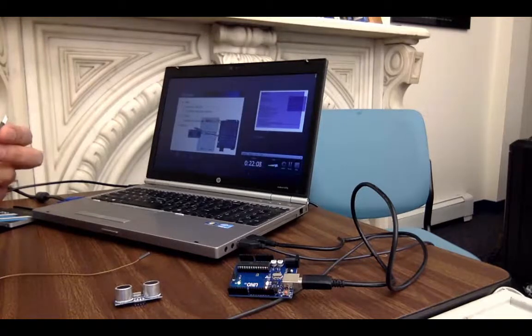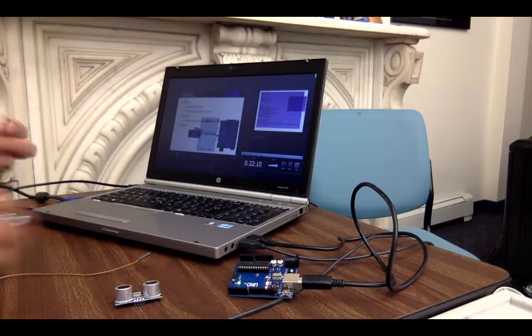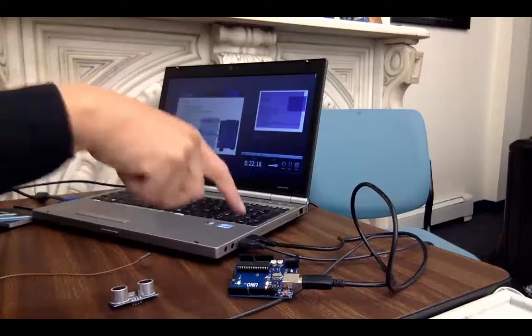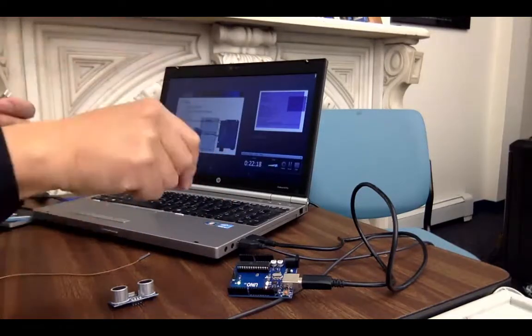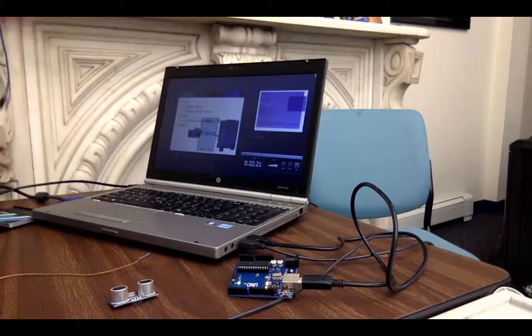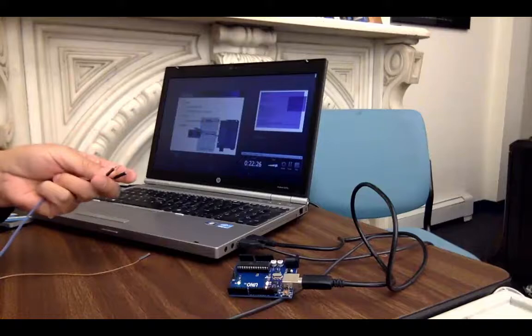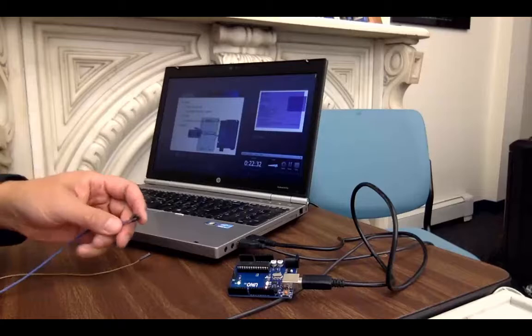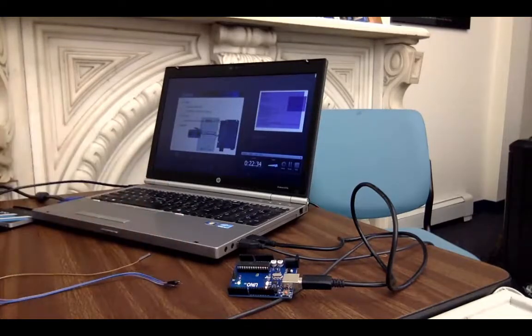And then be careful that the cables are plugged into the right connection. Okay? If there is a ground, it should be ground to ground and voltage to voltage. And then this sensor has 4 pins, so 2 pins for the data, right? Remember that this ultrasound distance sensor needs to take 2 data.